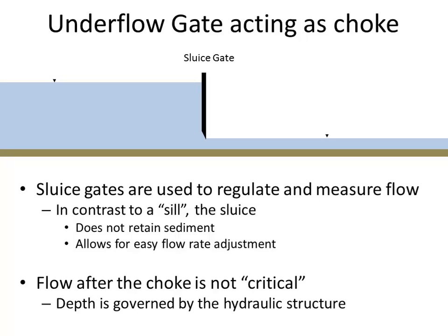And the other advantage is that, remember that if we have the step up equal to or greater than the maximum delta Z, then the flow that goes over that will be critical. Remember, when choking occurs because of a choke, the water level will rise until there's enough specific energy to get up over the obstacle. But it will only rise until you've got the critical depth over the obstacle.